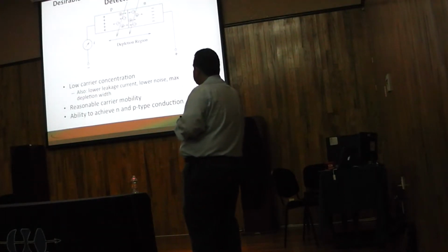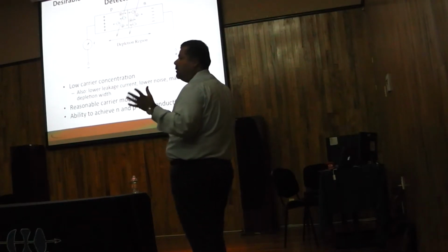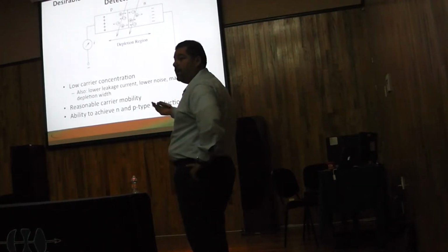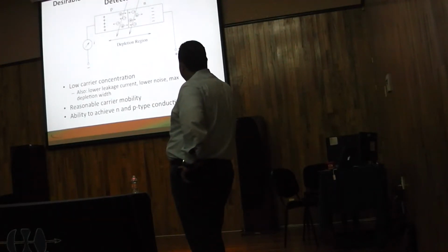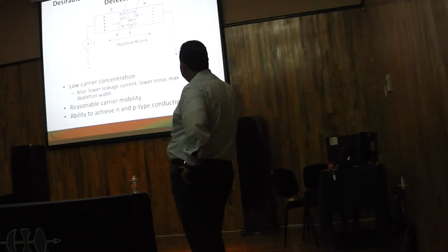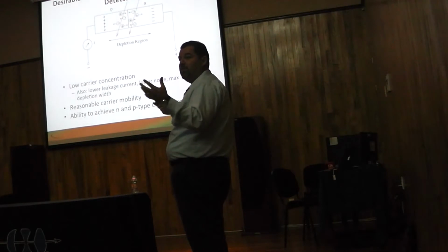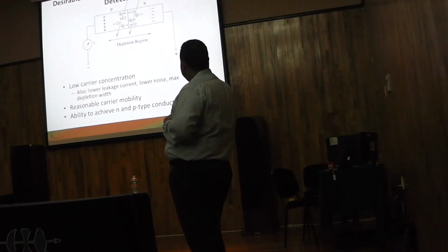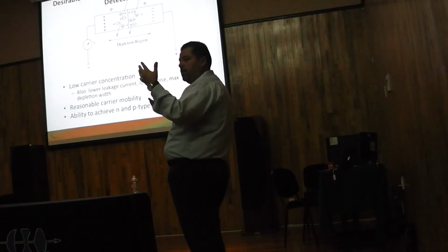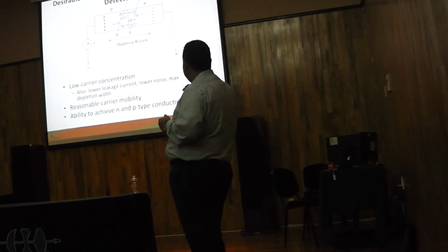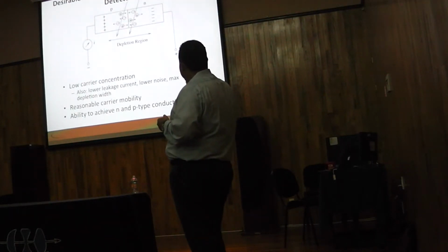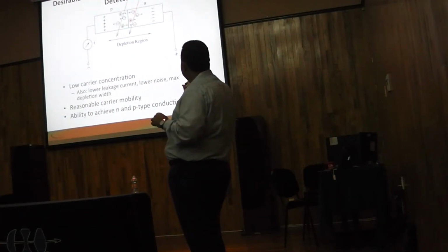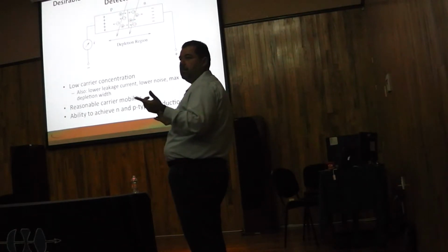And the detector that I will be showing you has a very simple concept. We have a p-n junction diode, or we might have a p-n junction or an avalanche diode. This is the metallurgical junction, so we have the p-type material, we have the n-type material. Now you understand why I'm very interested in N and P, because that will help me do this sensor. Then we generate what is called a depletion region. That depletion region is when the N and the P combine. When the ionizing radiation passes through, it will generate electrons and holes that I can collect on either side of the detector. Okay, that's the concept.